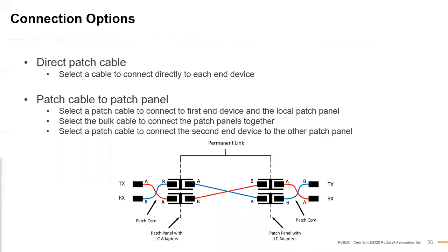So there are times where it is beneficial. Direct patch cables, especially within a panel, make 100% sense. But when you're going from one panel to another, external, especially if it's a long distance away, it makes sense to do the backhaul, do that permanent link.